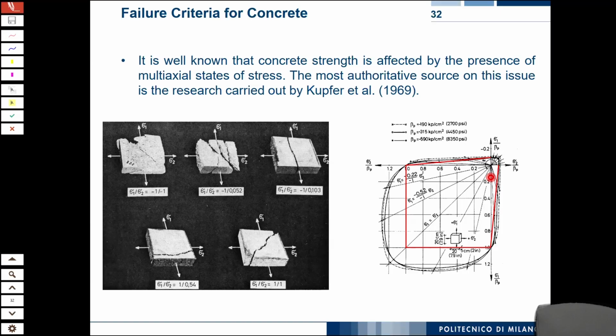And interestingly, the best situation is not when you have a 1-1 ratio. It's close to 1 to 0.55, 1 to 0.6. Because if you have 1-1, you already start engaging the material in both directions in the same way. So no direction can really fully help the other.